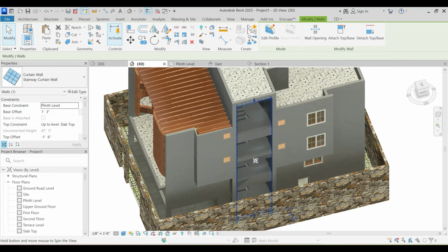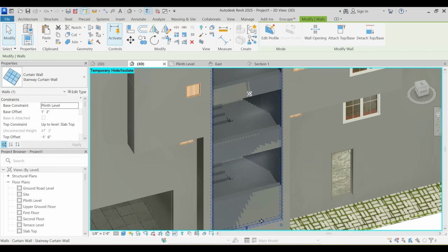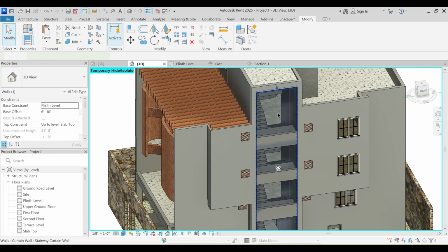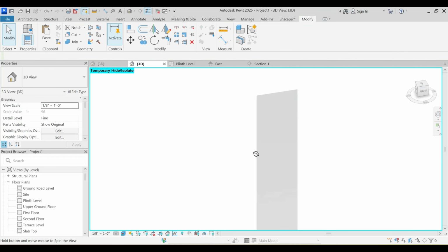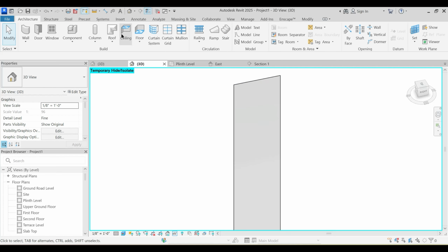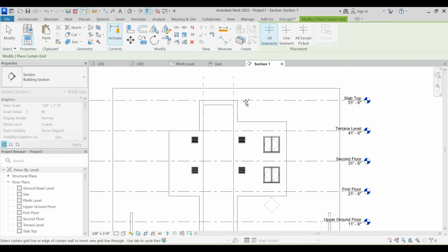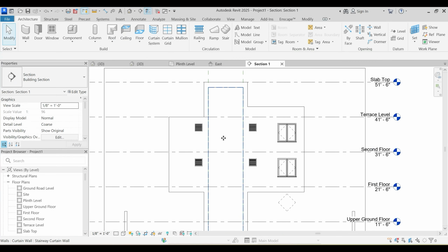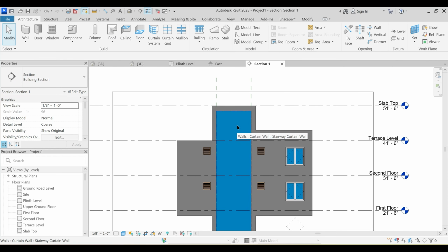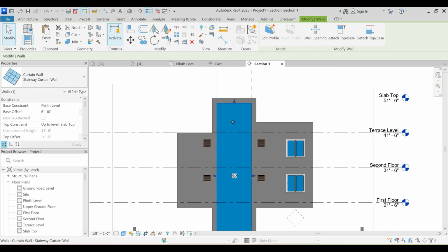And let's see how it has been laid. So here, this should elevate till this point. Okay. And herein, now you can hide. And I will show you now how you make a custom division within the curtain wall. So just go to architecture and grid. In order to do that perfectly, we will go in this elevation and we can have some reference of where to perform that particular division.